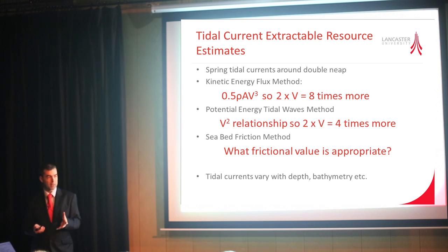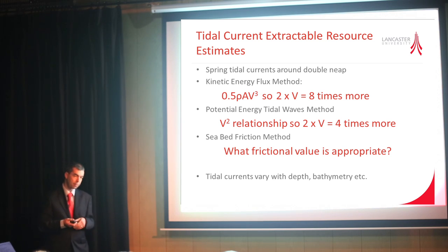A third argument is based on the seabed friction that we get from the tides, that as water moves over the seabed, it dissipates a certain amount of energy due to the friction effect of the seabed conditions. If we start extracting energy out, or kinetic energy out from the flow, there's less to be dissipated on the seabed, so potentially we can extract more than we thought we could without damaging the local environment.